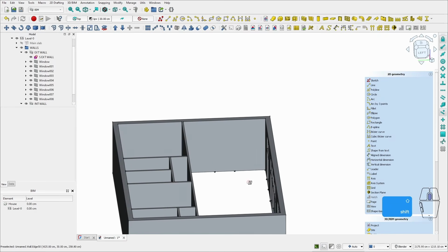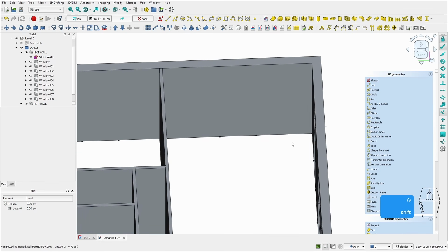Before I let you fly the coop, let me show you how to place a window at a specific height from the ground. To place the window at the correct location, begin by snapping it to the reference point that you previously created within the sketch. Once the window is aligned with the reference point, you can then adjust its vertical position by modifying the z-axis value.